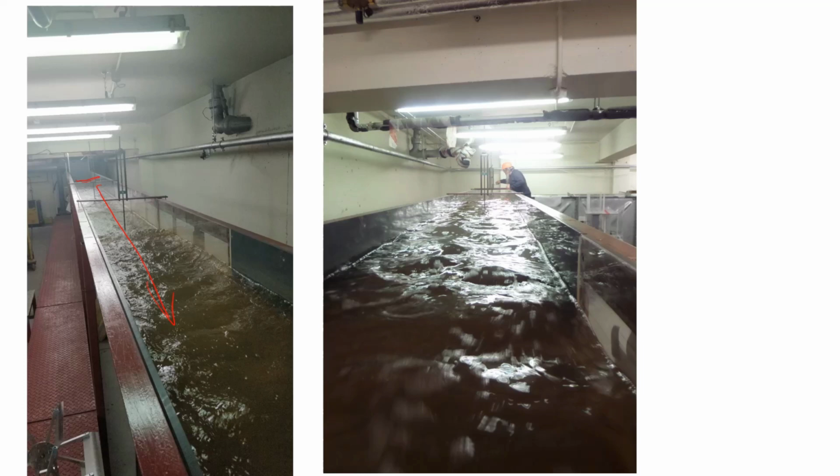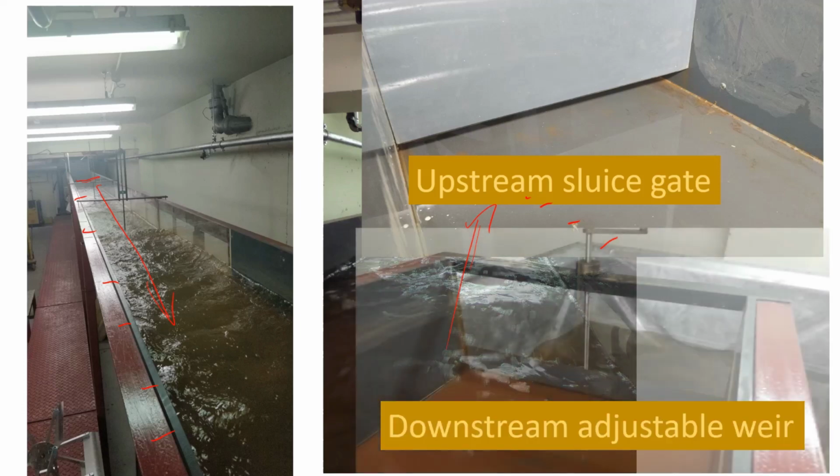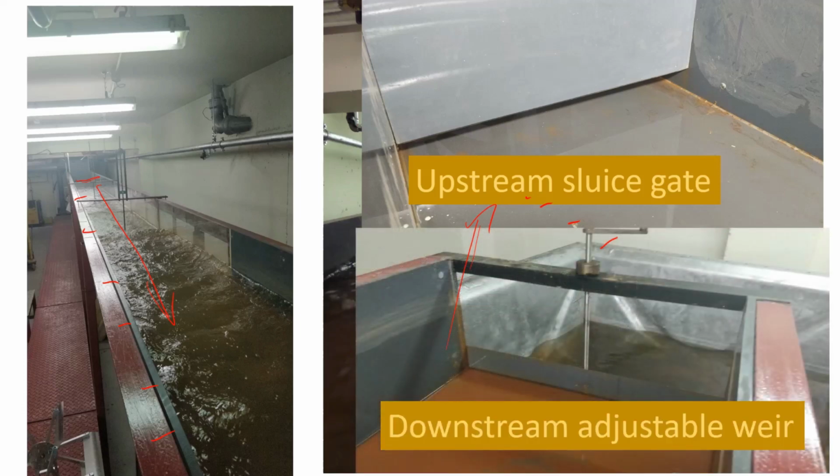So you can see how the water is flowing that way, and we're going to take measurements of the depth and get the flow profile all along that channel, and get this at every meter along here. 17 readings, it's 16 meters long. At the upstream end there's the sluice gate forcing low depth and supercritical flow, and at the downstream end there's an adjustable weir lifting the level of the water, so you get a higher depth of water at the downstream end.